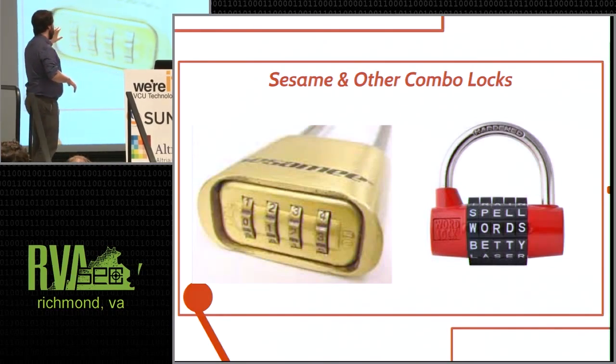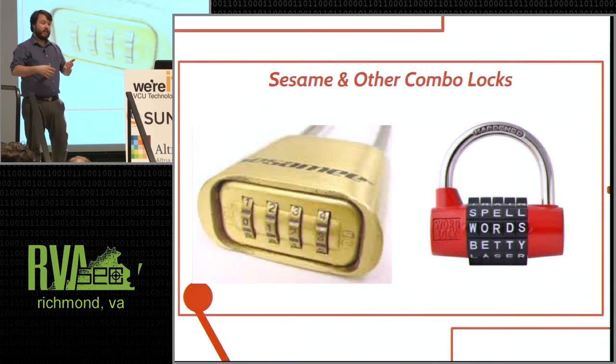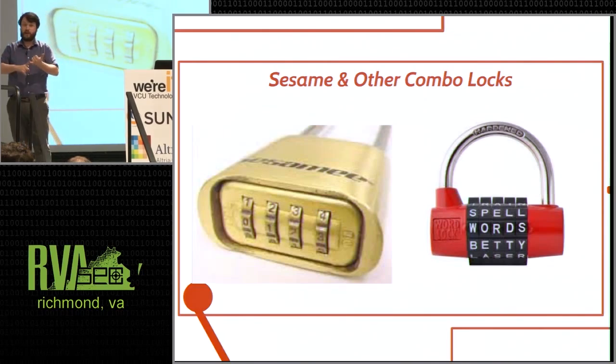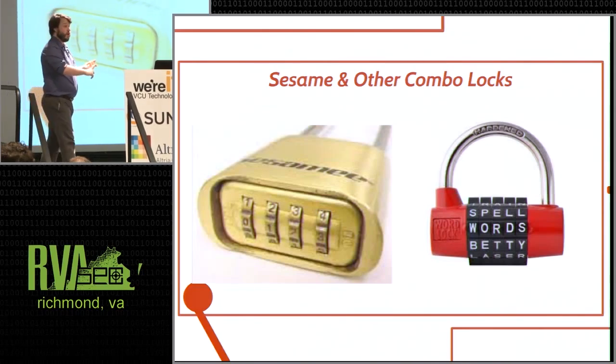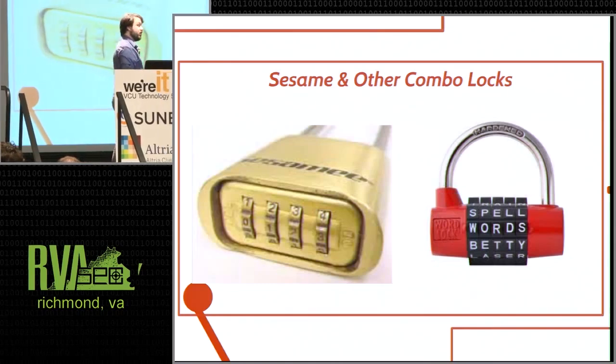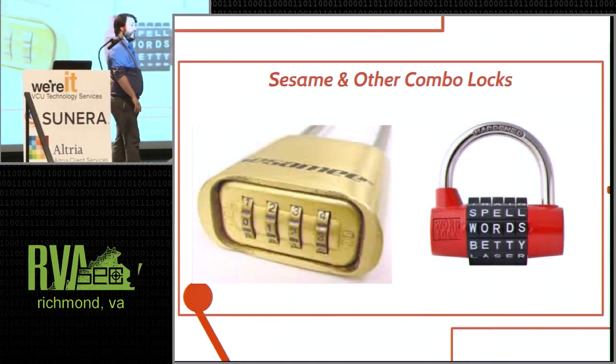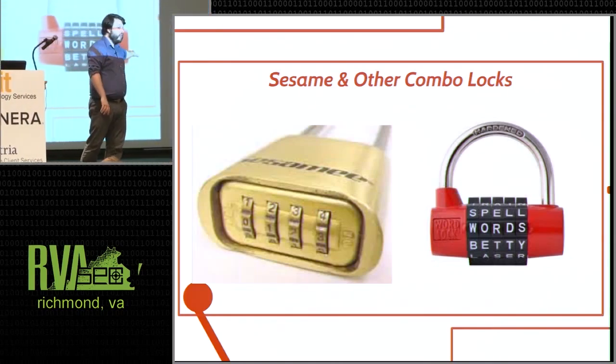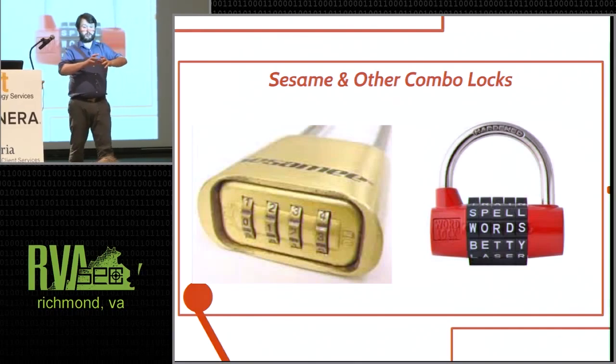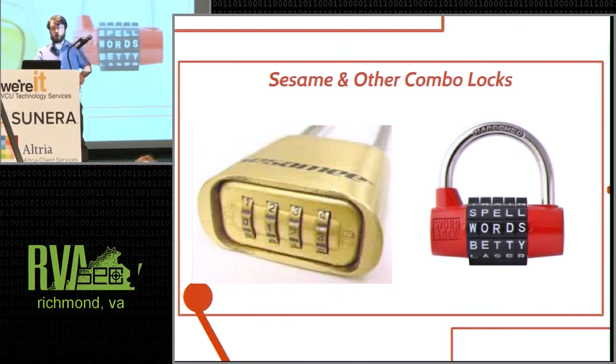Combination locks that have separated wheels, where you operate independently on every wheel in the combination lock, can be easily brute forced, and they can often be easily decoded. In particular, each of these works by having a gap cut out of some portion of the wheel or some other wheel that they're attached to.